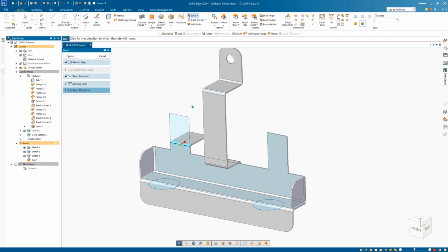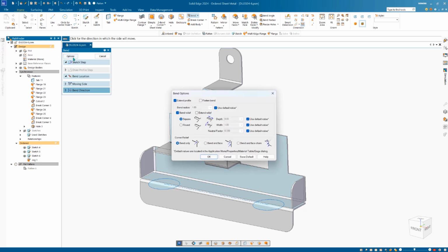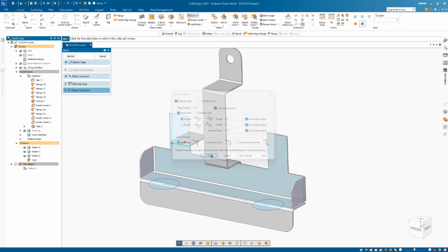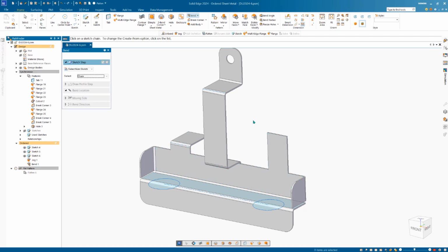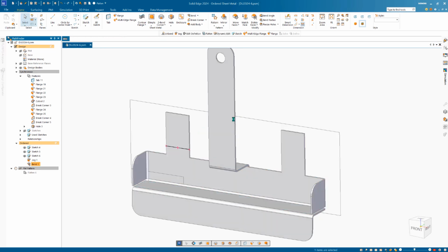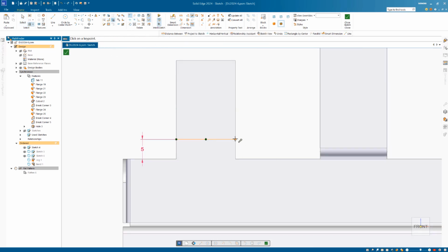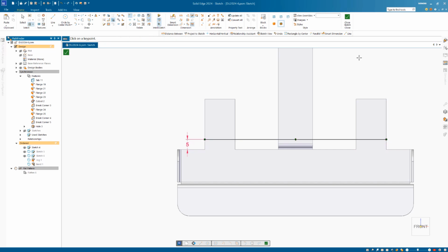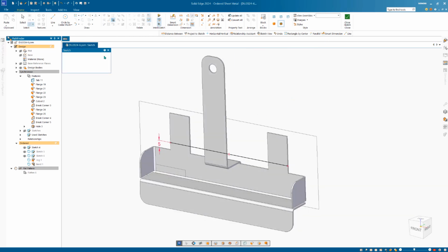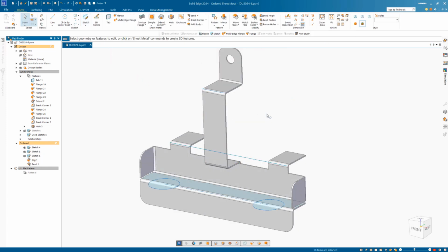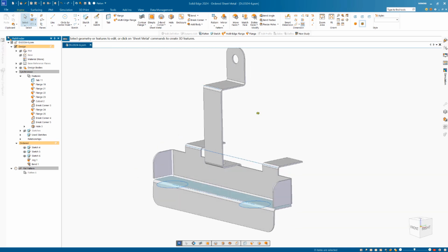Next we're going to do a bend. So here we've got a sketch, and because we've got a jog in the middle, our extend profile option doesn't work. So what we'll have to do on there, if we want to go and bend this other tab, if we edit into this sketch, do a quick fence select, remove this connect relationship from this end, and then use the connect command to join this up to there. We could have just dragged the endpoint as well, but there's several different ways of doing the same thing. And now that's going to go and bend across on there.